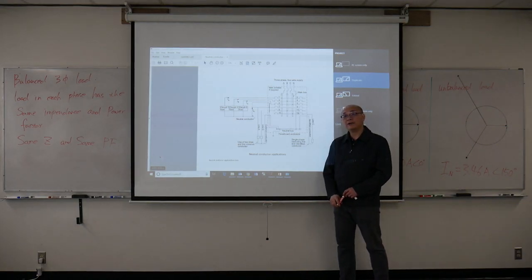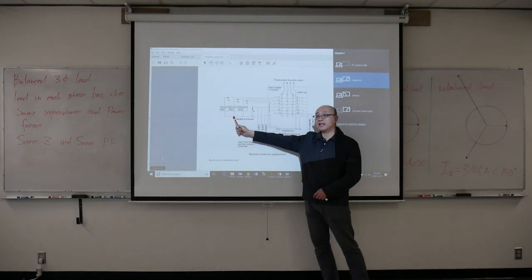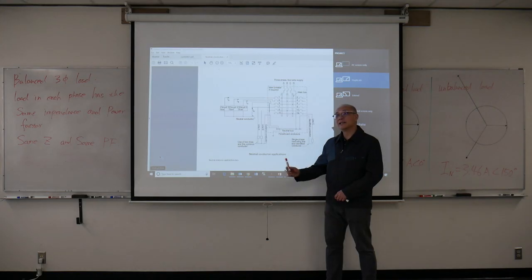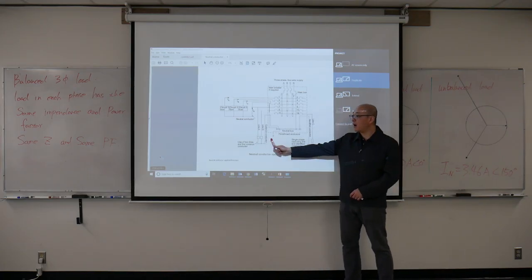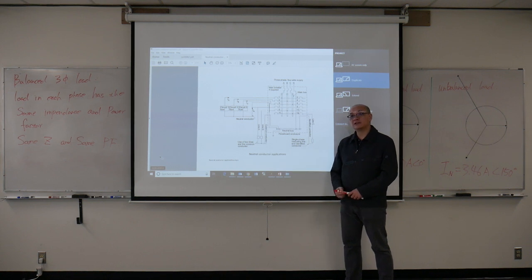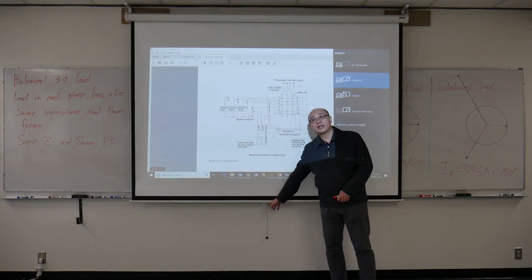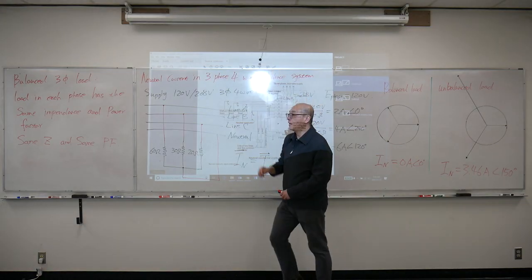I can give you a summary. In three-phase 4-wire, if the white conductor is common to all three-phase loads, then that's a neutral conductor. And in single-phase 3-wire, which you learned in year 1, that's a neutral conductor. Other than that, all the white conductors are not neutral conductors. So now we understand the neutral conductor, we can do our three-phase neutral conductor calculation.